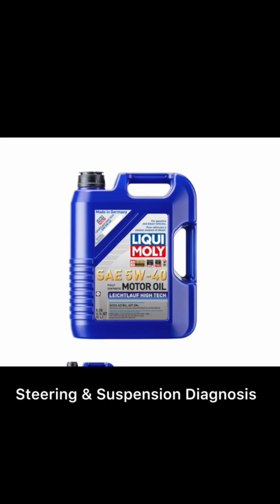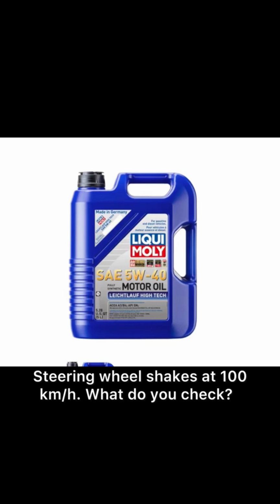Steering and suspension diagnosis: steering wheel shakes at 100 km/h. What do you check? Wheel balance, bent wheel, worn tie rod ends.